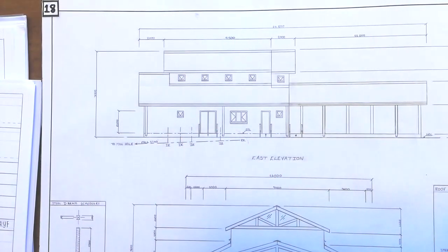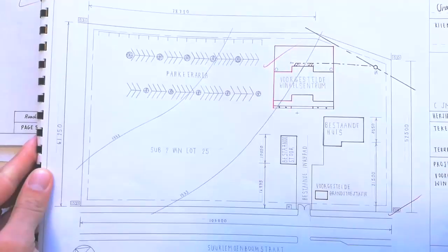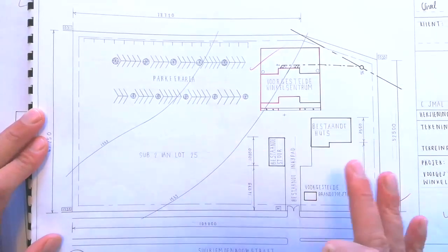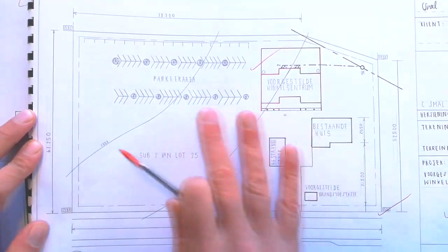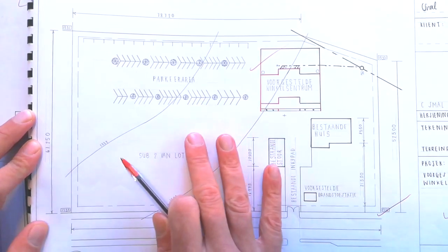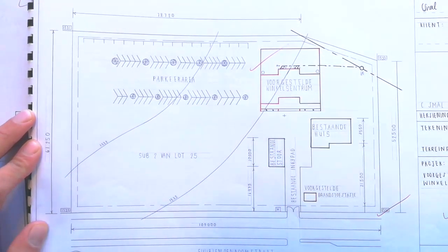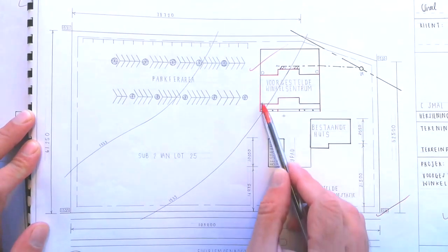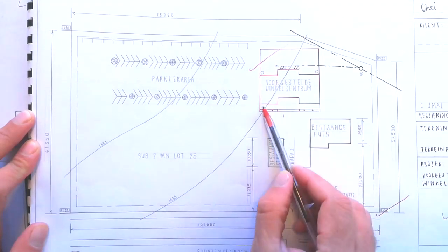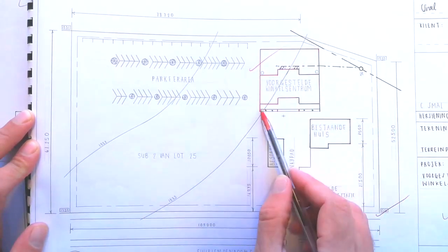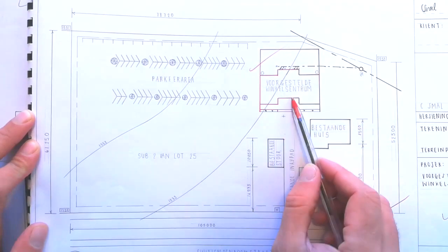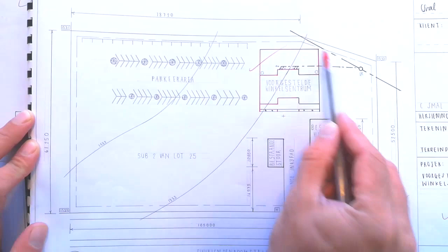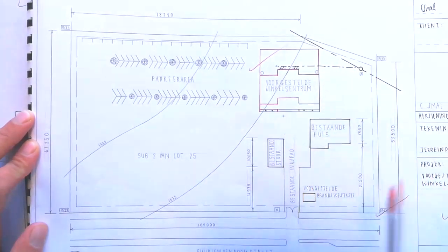Okay, last but not least, we're going to look at a couple of site plans. So the big thing here is to copy your site plan, and this is again an example of a previous year, so yours will look different, but copy your site plan with as much detail as the one provided for you. And then the new dwellings, do yourselves a favor and just highlight that in red. That shows that you know the fact that new buildings on a site plan are going to be red. Sewer detail, that's going to be brown, so make a note of that and make sure you indicate that correctly.